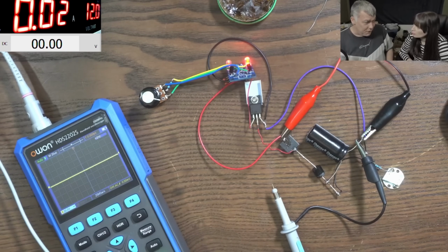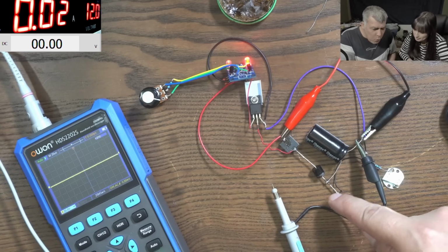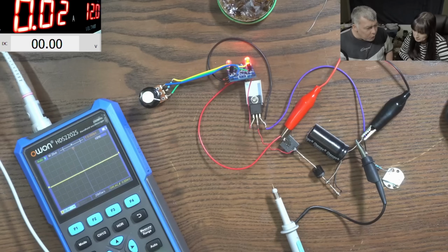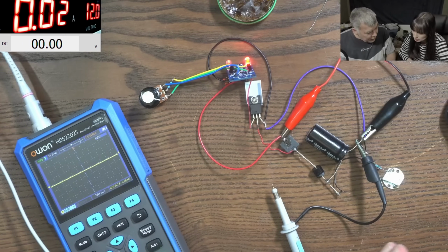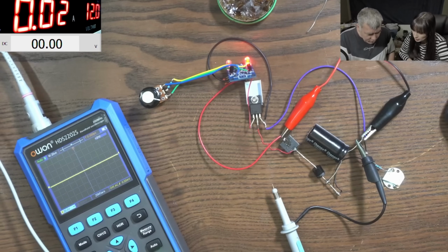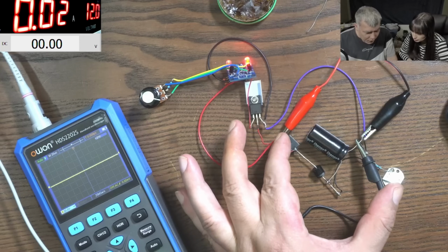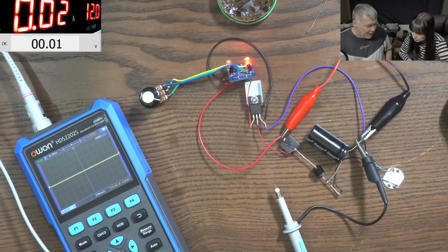But this one is not helping? That's the output capacitor. It is helping because it's smoothing the output voltage, your output of 30-something volts. That's the reason we use a capacitor, to smooth that voltage, because otherwise it will be switching, following the duty cycle. But we'll be using a capacitor from plus to minus, and that way I will smooth the voltage.